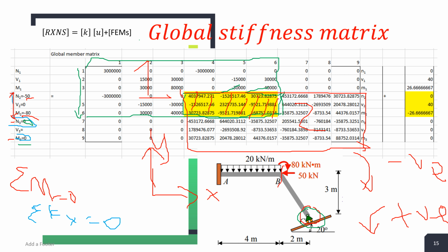But still something interesting also, at node A, these are the displacements, but we know the properties of a fixed end is that this is 0, the movement in the x direction is 0, movement in the y direction is 0, movement in the rotation is also 0, from basic understanding of mechanics of structures.